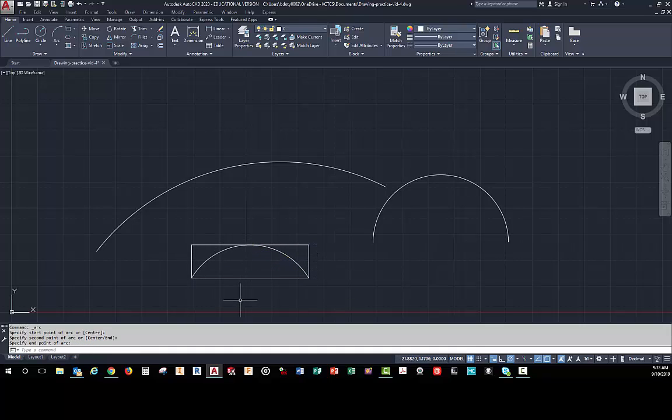And you're saying, hey, why does it do that? Well, those are object snaps, and that's something else that I will make a video and talk about as we move along. They're just really simple settings that you can pick on the little down arrow right here, and these are the ones I have set up: endpoint, midpoint, center, intersection, extension, and apparent intersection.